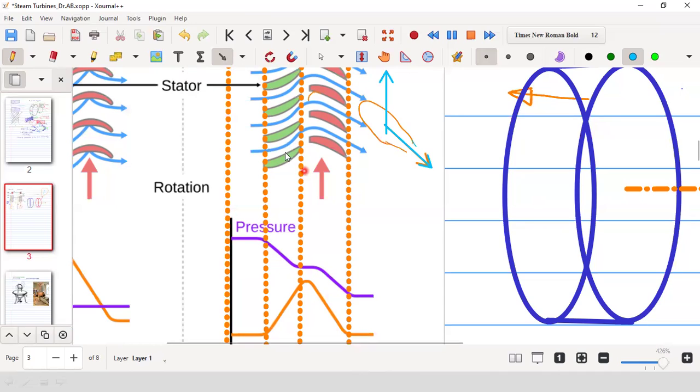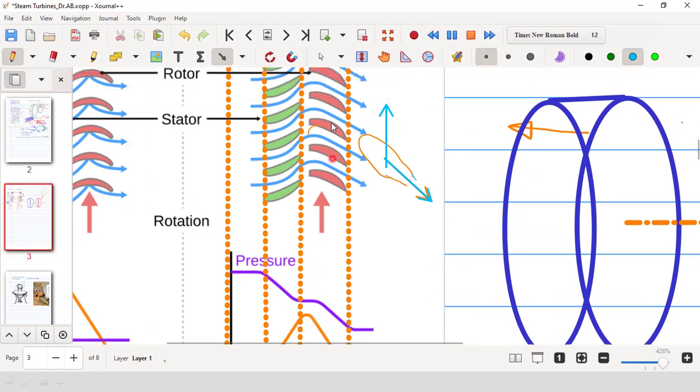The nozzle is static. So that means what? Even if there is a pressure drop, the nozzle will not move. What will happen? All the movement will be of the fluid itself. That means due to the pressure drop, the fluid velocity will increase. Okay. So the velocity of the fluid will increase, but consider the moving blade.